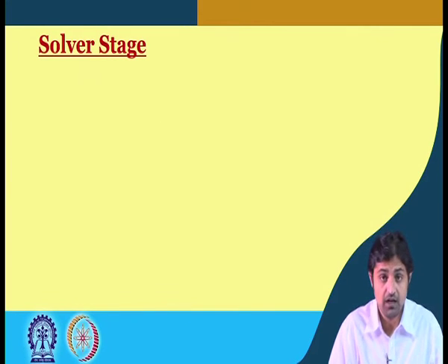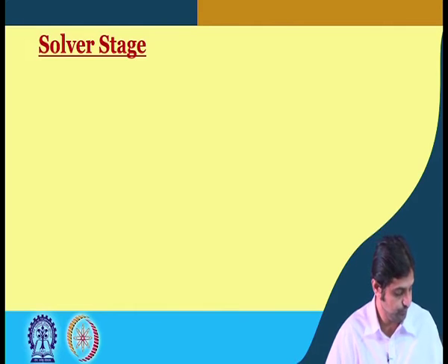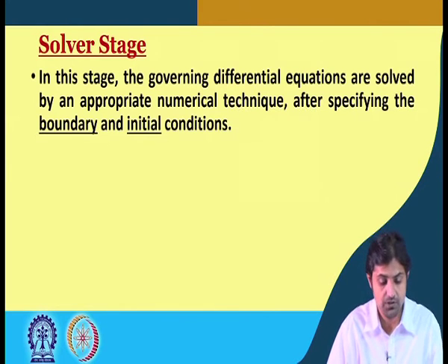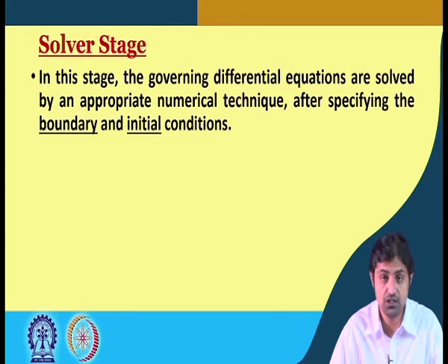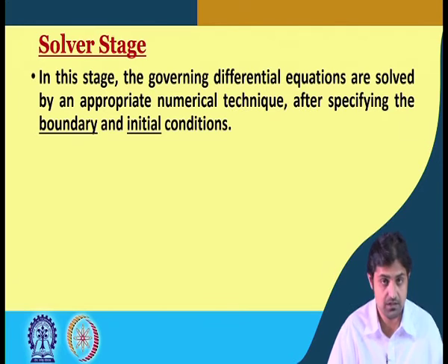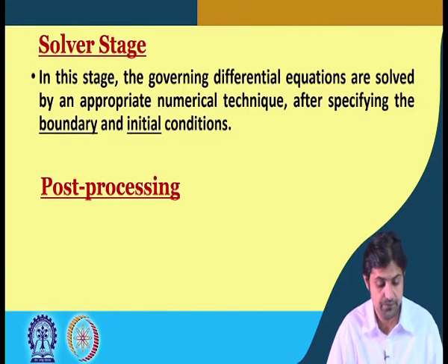So now after this grid generation, we come to the solver stage. In this stage, the governing differential equations are solved by an approximate numerical technique after specifying the boundary and the initial conditions. All right. So the actual real solution of those differential equations is done at this stage, called the solver stage.